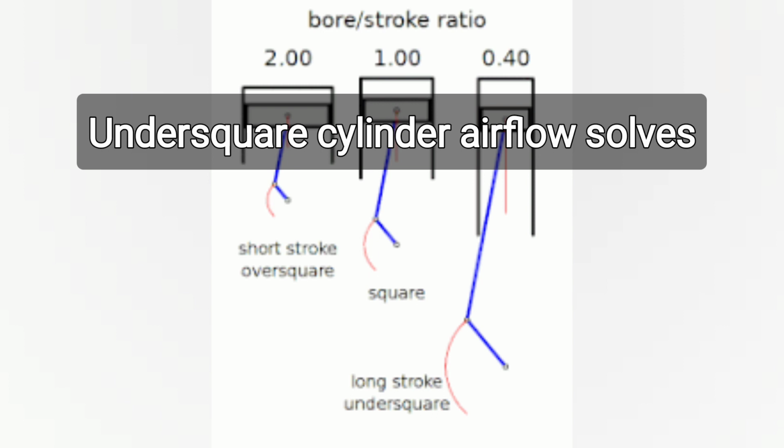But that's the undersquare stuff. Undersquare is effectively that. Oversquare is essentially a different type of thing entirely. Oversquares suck. To be fair, there's literally genuinely no way of getting around an oversquare issue of RPM. Right? I can't push materials past a certain point. I can't push friction coefficients past a certain point. There's nothing you can really reasonably do with an oversquare design past a point.